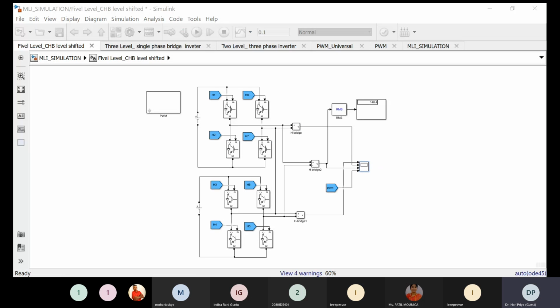Okay, fine. So this is a basic problem with this particular PWM. This is suitable for this, but when you go for higher levels, why would you have to go to reduced switch count configurations? Because of this. For example, M is the number of levels in the output voltage, and these are the switches required per phase. We talk about the cascaded H-bridge. Now for 5 level, how many switches are being used? 8 switches are used in each leg.